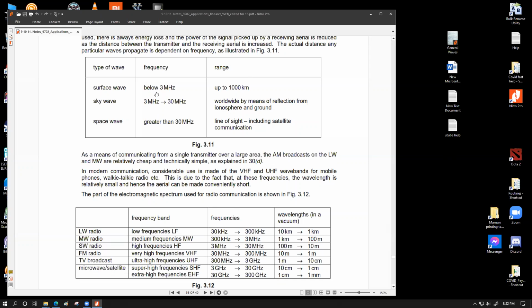So this whole range is below 33 megahertz. You can see that the starting frequency that we're choosing to do radio communication is from 30 kilohertz. If you wonder why 30 kilohertz, why not any smaller? Because 20 kilohertz is basically the last threshold of our audible range. If we choose a frequency wave that is within 20 kilohertz, then the carrier wave and the information signal will fall onto each other. We don't want that to happen. So we're choosing a bit higher side of the radio frequency.